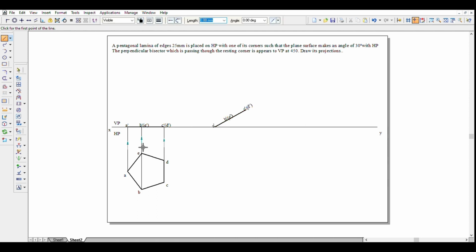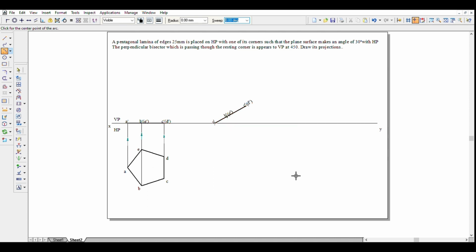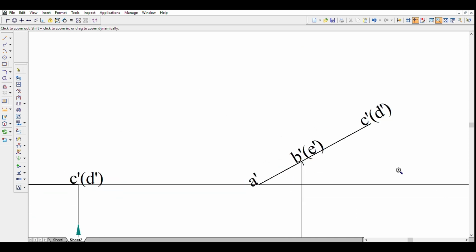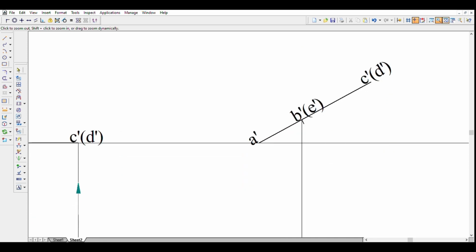We can just use the arc by center tool, check the radius, it's 14.69, so we can choose this as the center and we can type in the radius. We get to draw an arc at this point. We have a small arc that we have drawn at 14.69. Now we can use the endpoint tool and then draw an extension line from the arc. We can zoom in. Yeah, we can see the small arc I've taken here near B and we can fit it back.